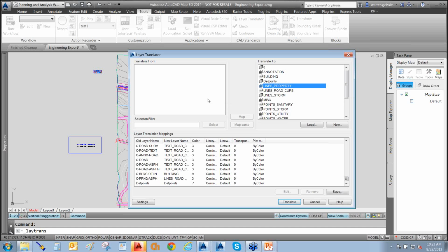Okay, so when I did this, I said, take all of the layers that have to do with my sanitary manholes, or my storm, as an example, the manholes, the outlets, the inlet structures, etc. For water, all the valves, all the fire hydrants, everything on all 20 layers. Just take every one of those appurtenances, put them on 1 layer. That's all I'm concerned with, 1 layer, because it's got to go here.